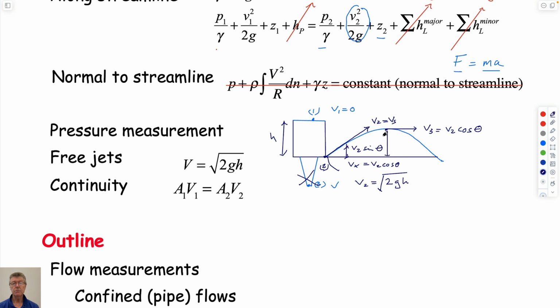So we have one term to solve for. We get that elevation. And as we talked about last time, if we're squirting directly upwards, then this will go exactly to the height of the level of the water. At this level, the streamline velocity will be 0. It'll be decelerating as it goes up, using up all of its potential energy. It'll stop here because it has no potential energy, z, and the velocity is equal to 0, and it'll start falling down again. So that's the same that's happening here.